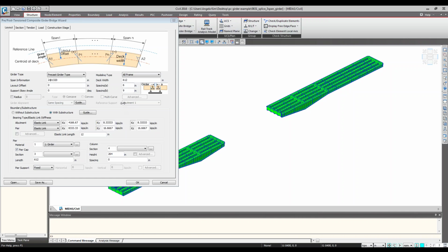The wizard is built to be most comfortable and simplest, not really distracting you for more than 90% of the cases. But if you happen to have a case where details like A and B are varying over here, then you can always create a model first, and using the manual node and element, move node, this type of functions, you can really easily tweak that. I'll follow up with you personally to give you a little more detail about it.